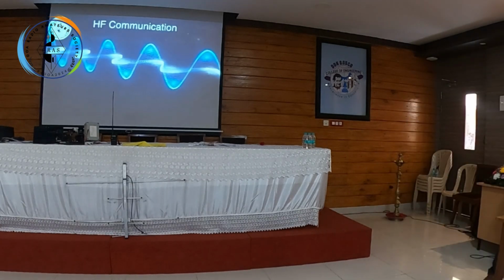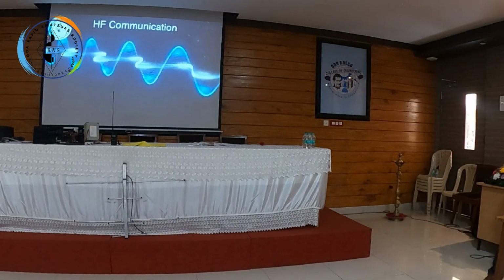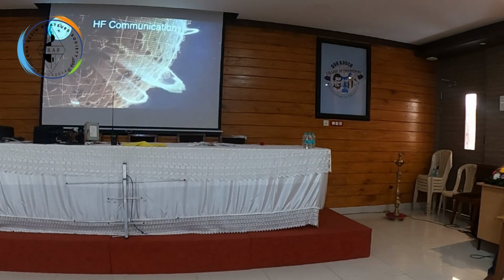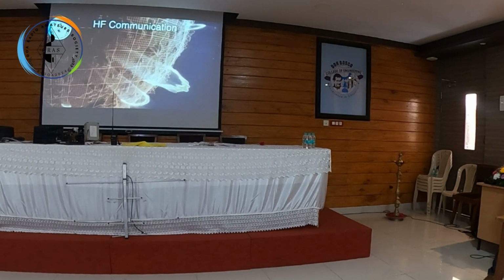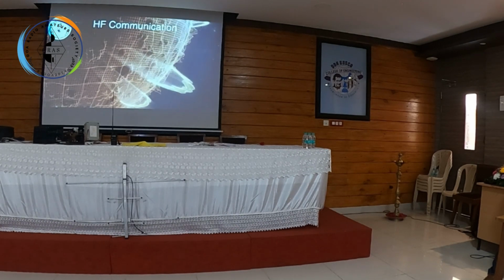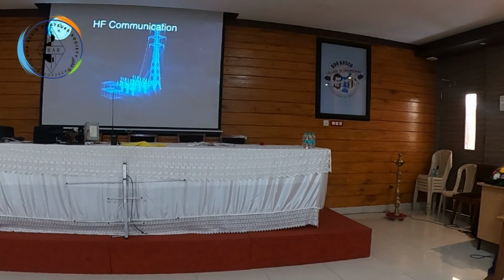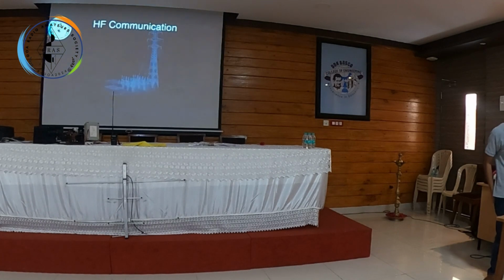What are some of the other factors that can affect HF radio waves? Solar flares can alter the refracting property of the ionosphere. 11-year solar cycles can either hinder or improve the HF radio waves. And finally, something man-made, such as power stations which produce electrical noise, can affect the reception of HF signals.